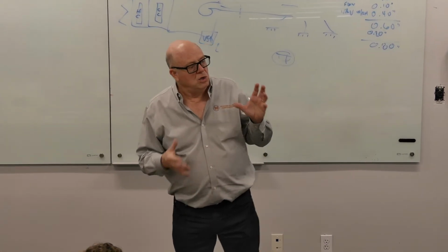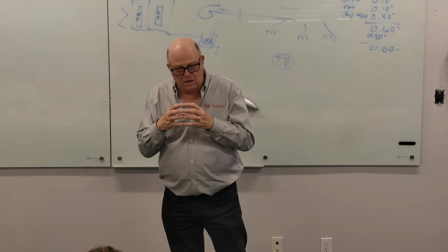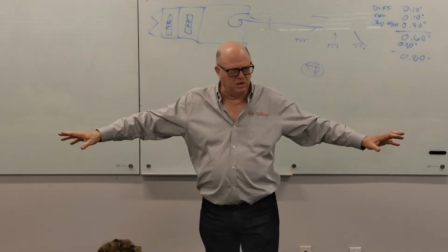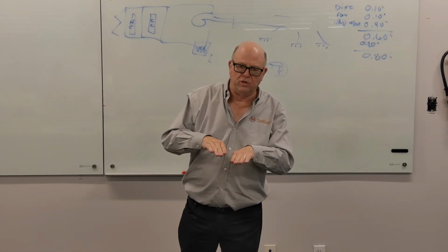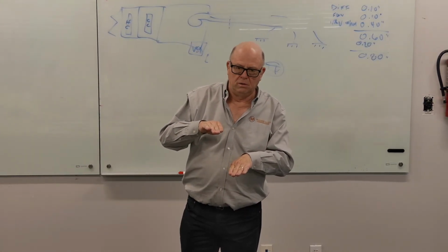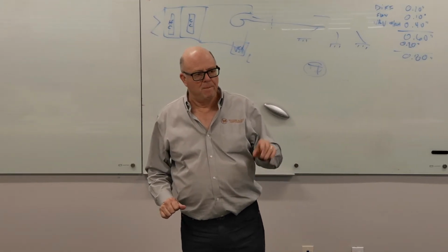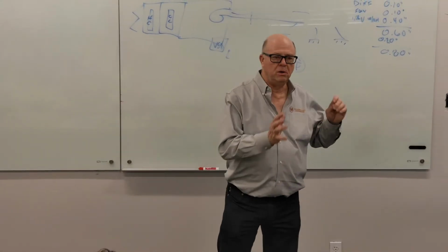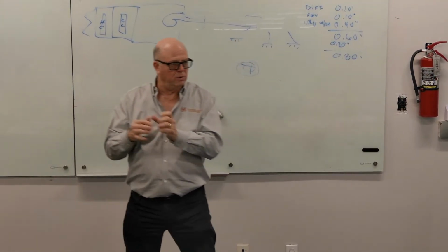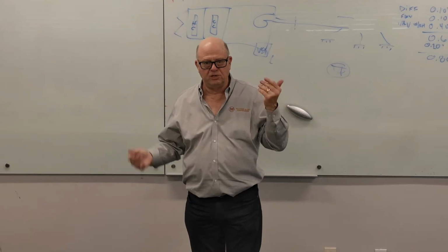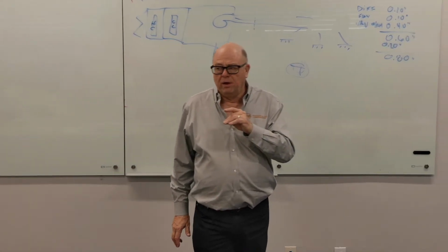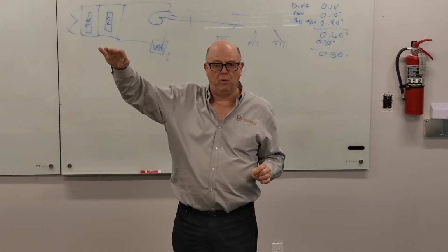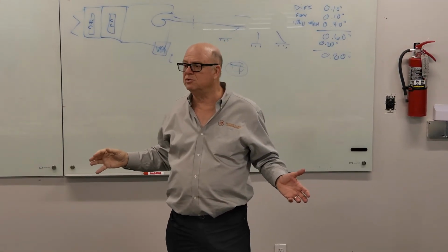And so you can use that data, and you know that you're meeting the cooling load, no problem. Well, now you can start to jack up the water temperature. But I think I told you, and a lot of people do that, but I think I told you that you probably use more power on the fans than you do on the refrigeration plant. It's usually like 60-40. And so where you're really better off is keeping the leaving air as cold as you can get away with without having draft complaints.